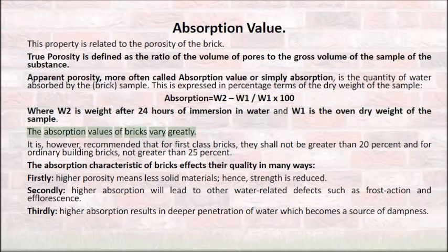The absorption values of bricks vary greatly. It is, however, recommended that for first-class bricks, they shall not be greater than 20%, and for ordinary building bricks, not greater than 25%. The absorption characteristic of bricks affects their quality in many ways.